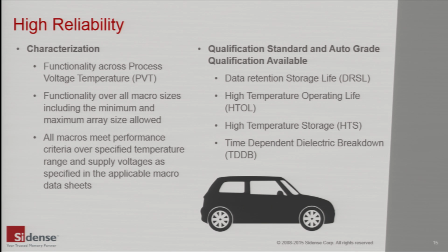Okay, let's have a look at reliability. Sidense OTP macros undergo a very comprehensive and rigorous qualification program. Qualification typically follows JEDEC standards and foundry standards like TSMC 9000. Sidense develops test chips that are manufactured in the target fab process and typically include all macro blocks covering a range of macro sizes. Characterization is performed on slow, typical, and fast split lots, typically over 3 manufacturing lots, in order to cover all possible processing variations.